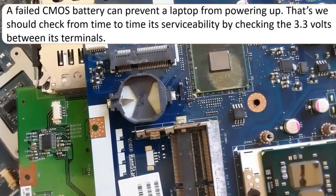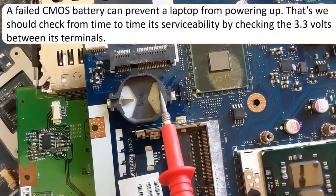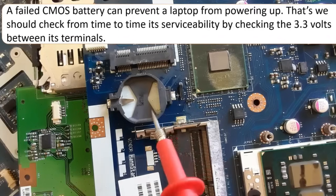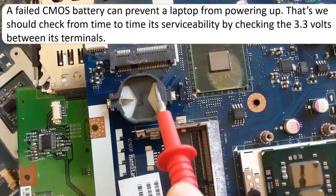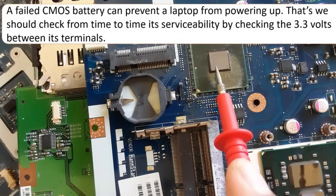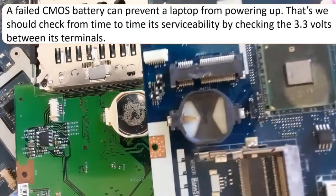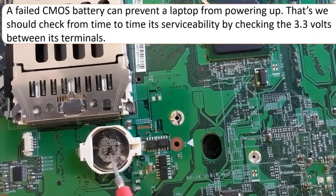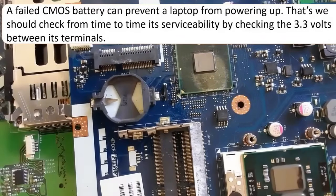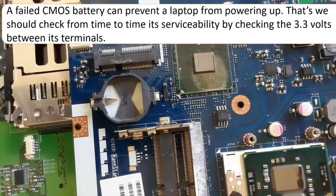So always, as I told you, if you understand one motherboard, you can understand every laptop motherboard, whatever its type, is it old or newer, etc., because the working principle is the same. As you can see, this is the positive terminal here, and the CMOS battery also is usually near to the ICH. So the CMOS battery, the ICH, the BIOS chip, and the SIO are usually near to each other.